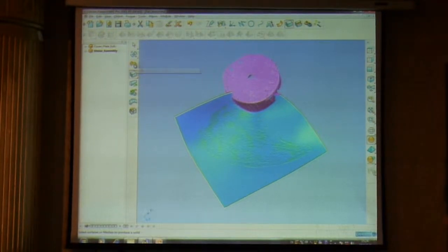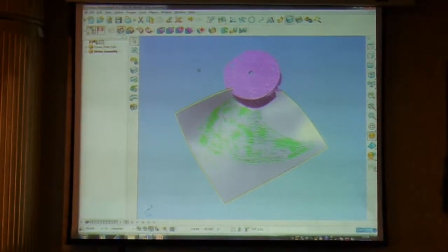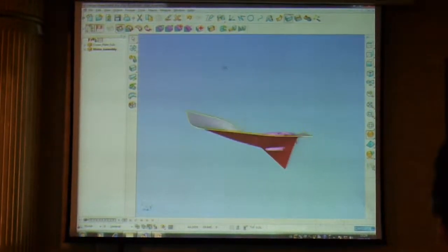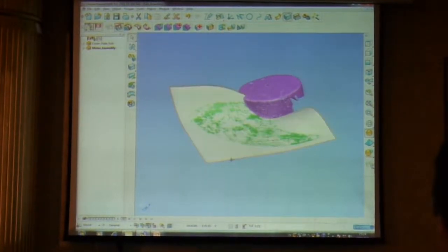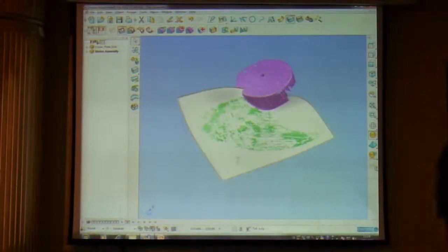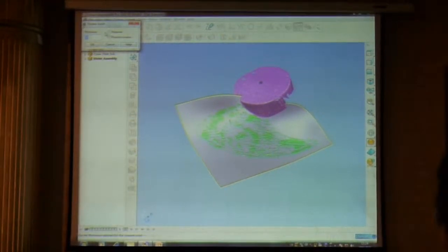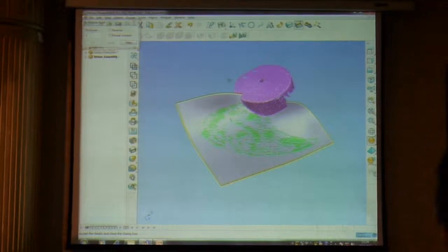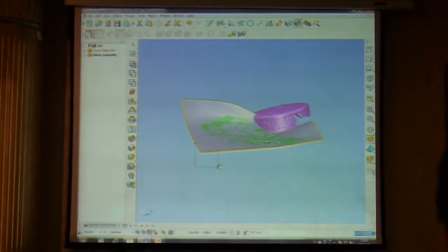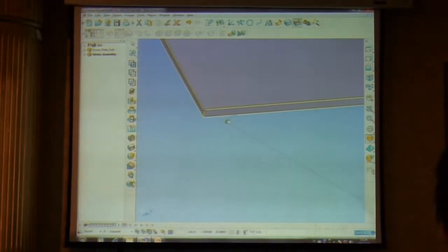Now the first thing I'll do with that surface is convert it into a parasolid. So this is now, as Vineet mentioned, an infinitely thin parasolid model. So the first thing I'll do with that is to give it a thickness, and the thickness of my blade is 2 millimeters. Okay, so now when I zoom in on this edge, you can see we have thickness.